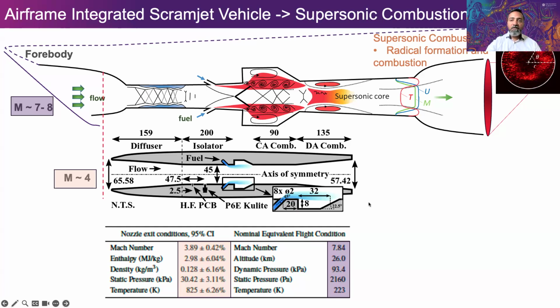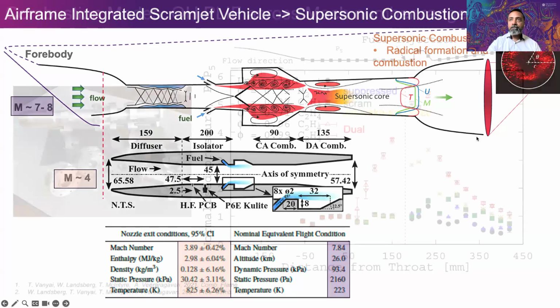So that is in every series of experiments, and I get this question as well. You're testing with a Mach 4 nozzle, but you're saying it's a scram mode combustor. Yes, because we've made sure that the enthalpy of what's coming here matches what would have happened at this station in a real scramjet. So that's what we're doing.